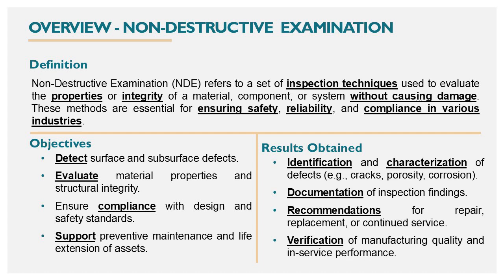Results obtained from non-destructive examination or NDE include identification and characterization of defects, such as cracks, porosity, corrosion, documentation of inspection findings, recommendations for repair, replacement, or continued service, and verification of manufacturing quality and in-service performance.